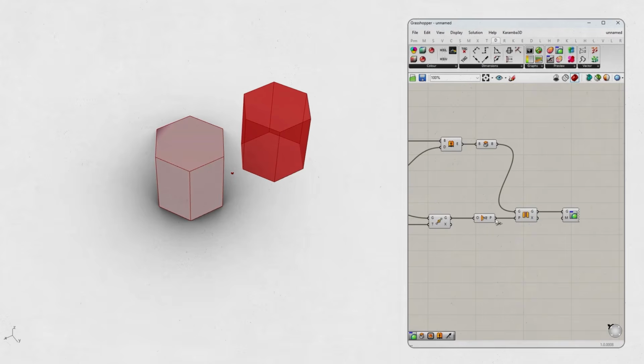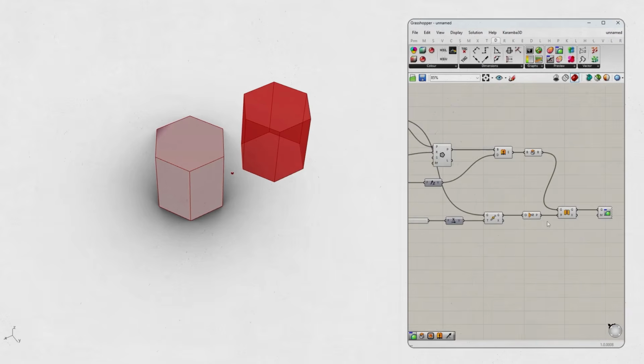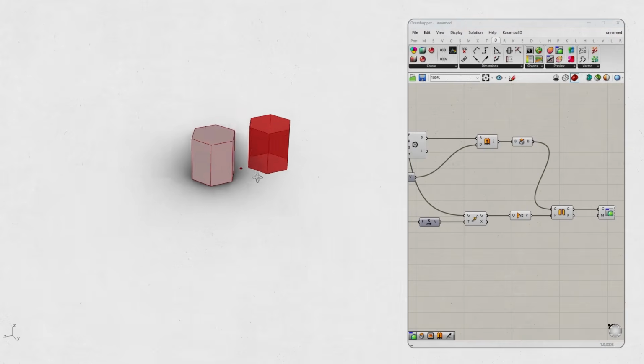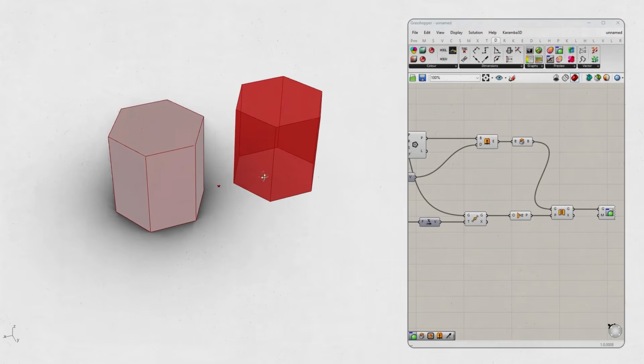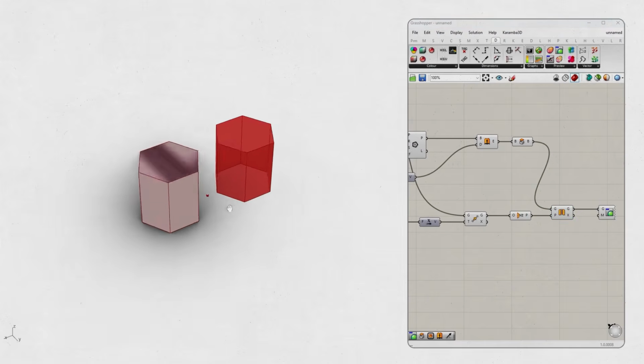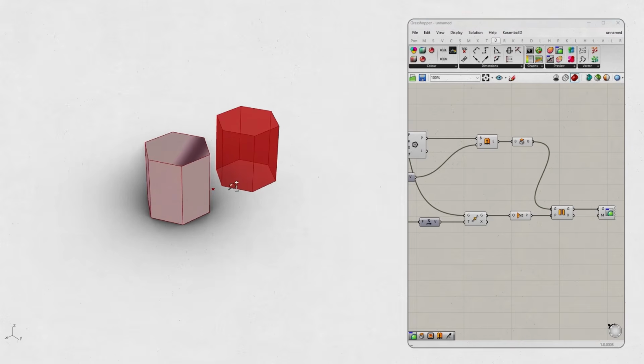Inputs. Geometry is the object or curve you want to reflect. Axis is the line or axis of reflection around which the object is mirrored. Optionally, you can use a plane instead of a line for the reflection. The output is the mirrored geometry. The original object remains unchanged, and mirror generates a new reflected copy.